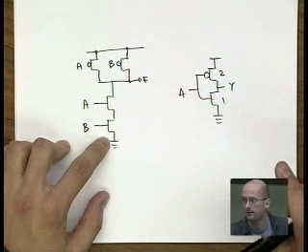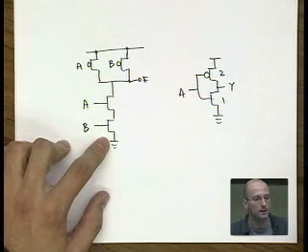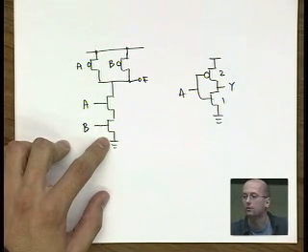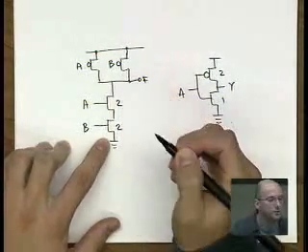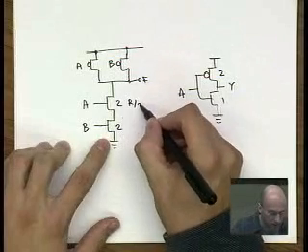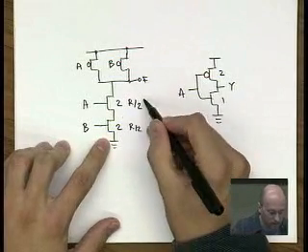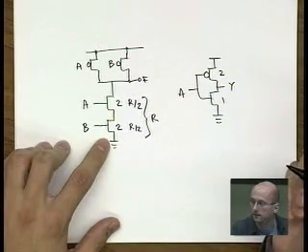It adds up, right? What's the impact of gate sizing on equivalent resistance? Correct. Everybody got that? So basically you have to double these two such that you have R over 2 and R over 2 resulting in net equivalent R.